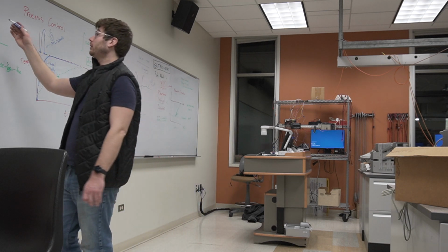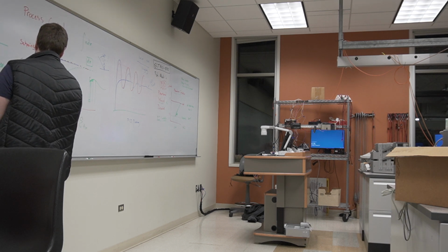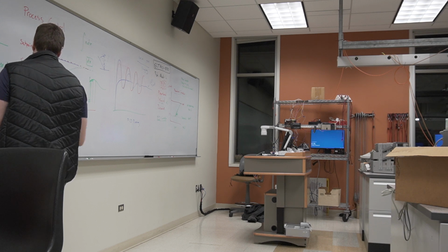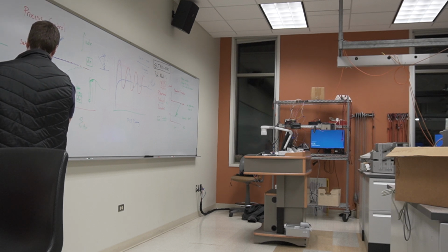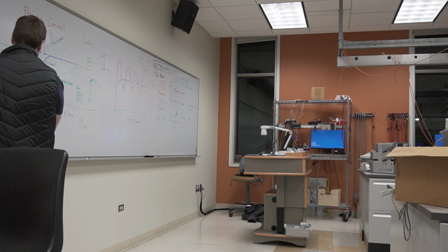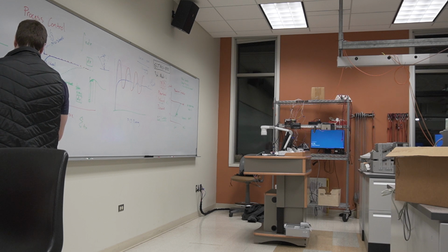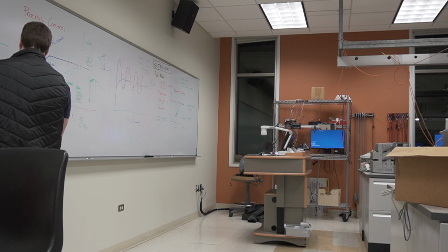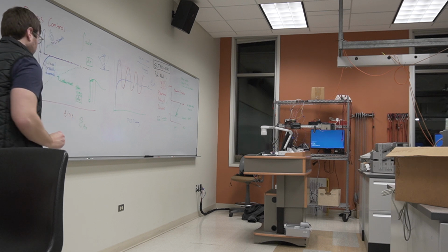So again, these are numbers. The thing that we wire up, eventually we will have a function block within our ladder diagram or within our function block diagram that will take a process in, and it would probably take a set point variable, and it would probably take a P, an I, and a D that you would wire in as variables.